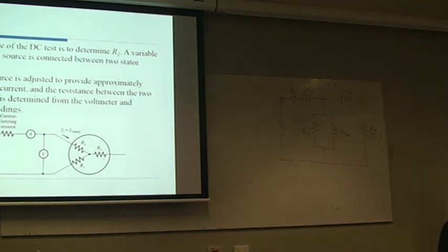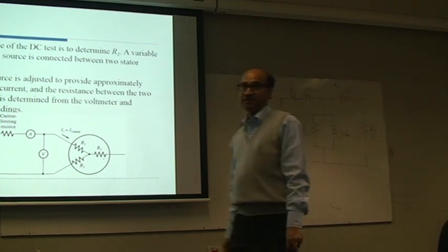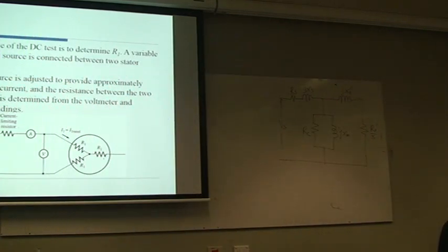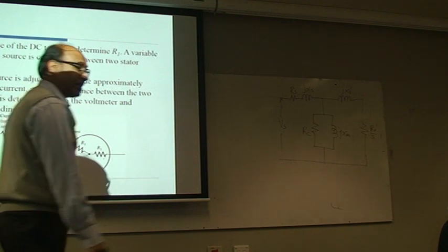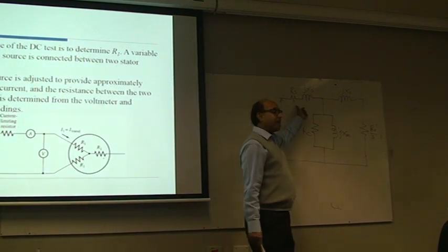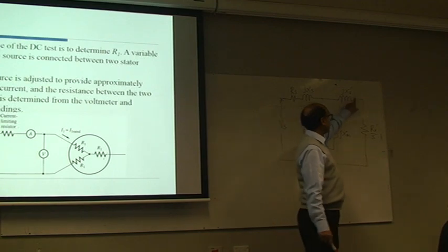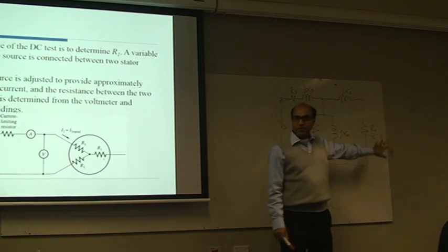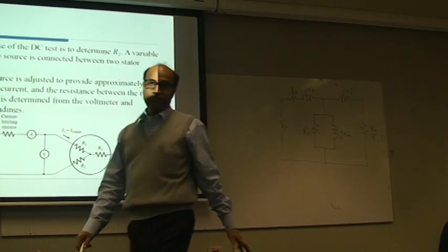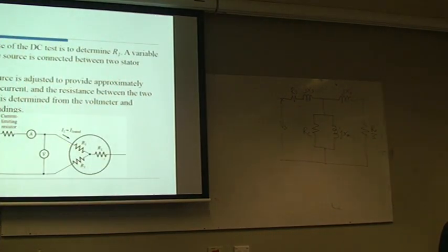Okay, I was thinking that was the load. Okay, so how many parameters do you have got? 5. 6. 7 if you count voltage. RS, XS, I don't think I count frequency. RC, XM, XR dash, RR dash. Slip is not a parameter you need to determine because that is the variable given. So, how do you determine those parameters?